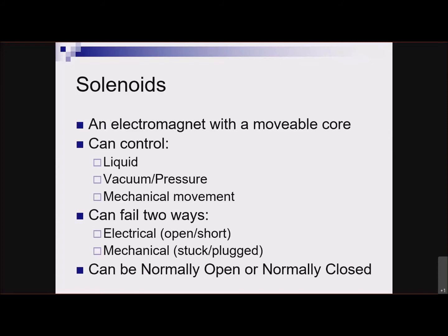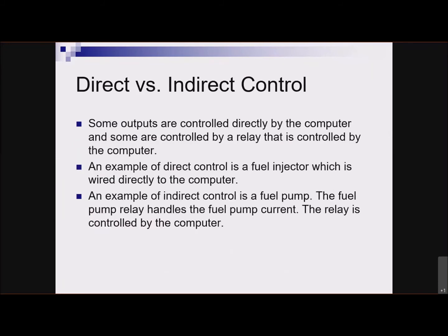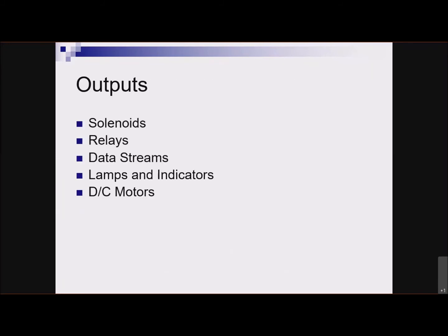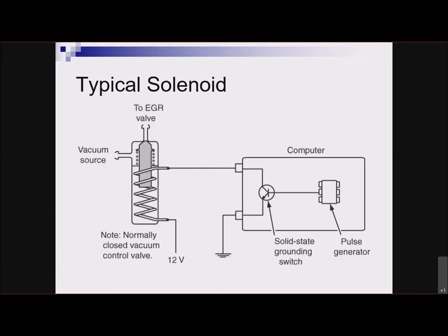So let me go back to this slide here, right? Yeah, I'll find it. This slide here. So imagine that this coil is fine, and your wires and your control of the solenoid, all this is working fine. But for some reason, either it's mechanically stuck, something's rusty, there's dirt in there, it picked up moisture, it picked up dirt, or it's mechanically plugged.